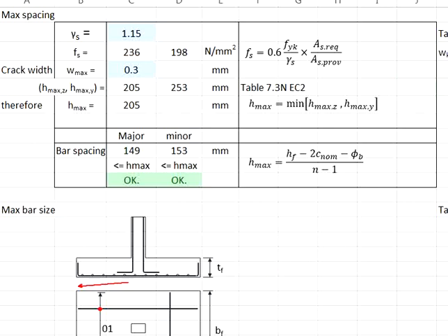Use the width of the peg footing minus 2 side concrete cover minus half size of the bar, half size of the bar, and the length left over shall be divided by total number of the reinforcement minus 1. The bar spacing that we are calculating is the center to center distance between two reinforcement bars.